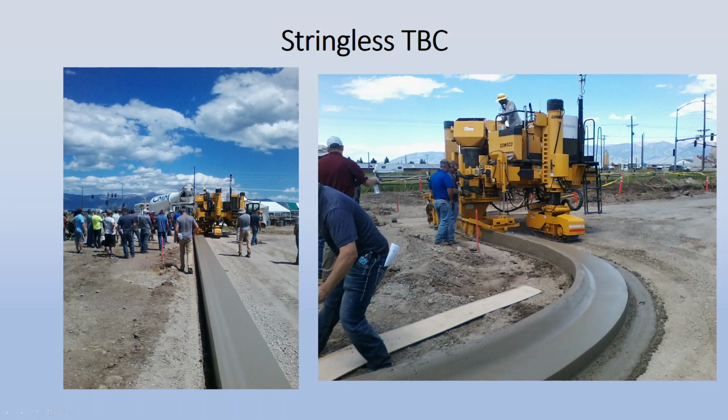But there's a laser level on site that's helping this machine control the vertical location of the curb being placed. And RTK GPS is controlling the horizontal location. It doesn't even need a string to go around curves. It's using a predetermined alignment, a digital alignment put in its computer to guide it around these curves. And it's an amazing technology.